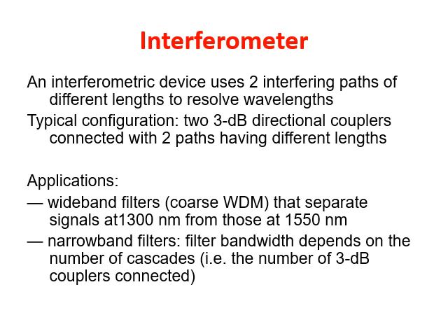Typical configuration: two 3 dB directional couplers connected with two paths having different lengths. So an interferometer is nothing but a kind of coupler which is having one particular wavelength, the 3 dB directional coupler, which is considered with respect to one example. As you can see at this point, a 3 dB directional coupler connected with respect to the WDM to connect from one into two channels or two channels into one channel. This is how we can make it.